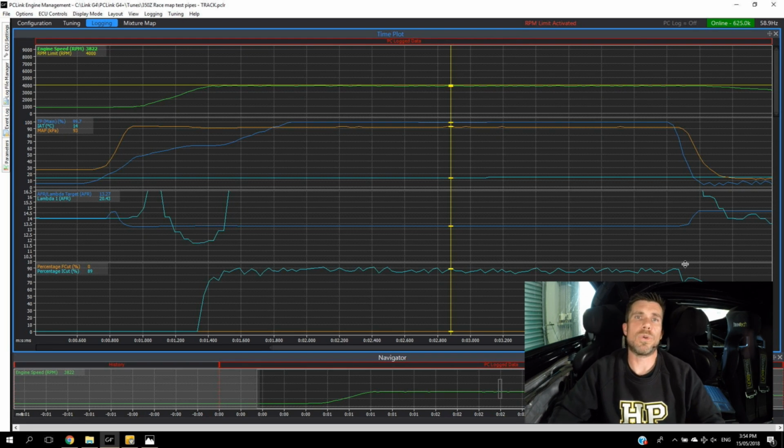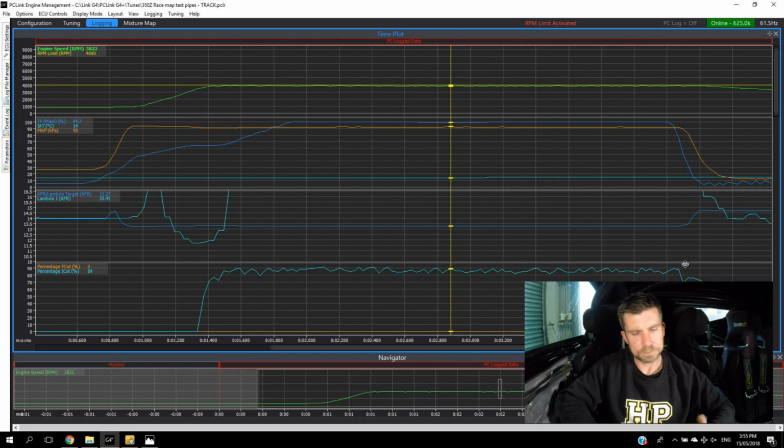So for example, if you're talking about a 4-cylinder engine, then just cutting one cylinder, obviously that's going to cut 25% of the engine's torque, and that's going to be quite a coarse change in engine torque. Whereas if we were, for example, to have an 8-cylinder engine, we're going to have finer control over exactly how much torque we are reducing from the engine. So you've got to be a little bit realistic about what you are going to be able to achieve.